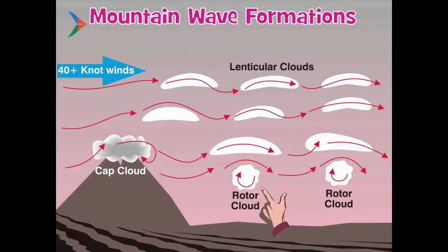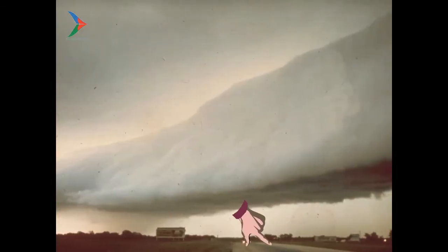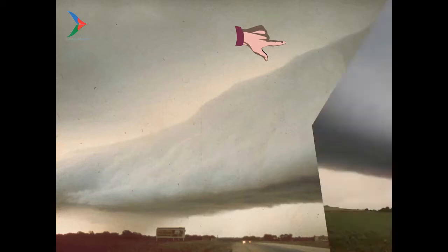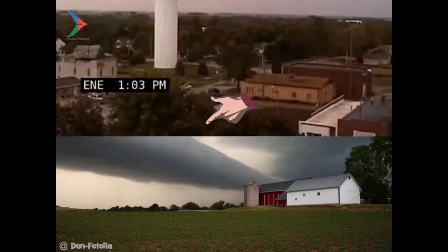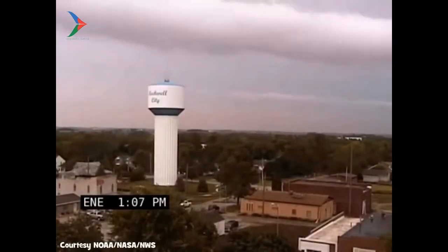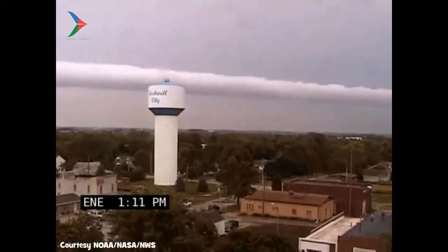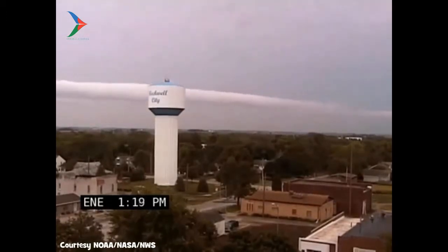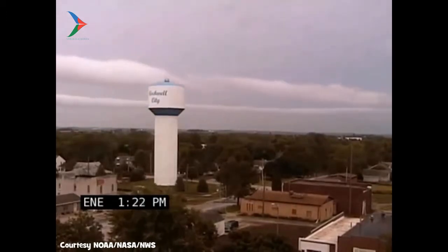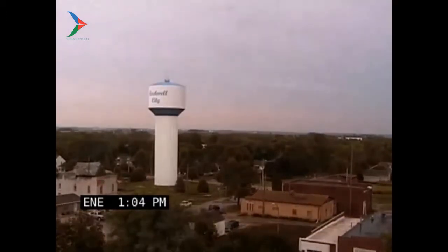Directly underneath the lenticular clouds, a small rotor cloud can frequently be found below mountain peak altitudes. Rotor clouds result from the frictional effects of the surface and a lifting action from the rising crest of air. Air velocity is slowed near the surface yet flows faster at higher altitudes. This adds a rolling motion to tubes of air similar to the forward motion of a baker's rolling pin. Long, cigar-shaped clouds form, each containing severe turbulence. These clouds are to be avoided like cooties were avoided in 6th grade.